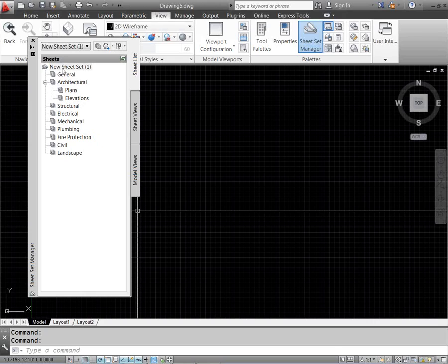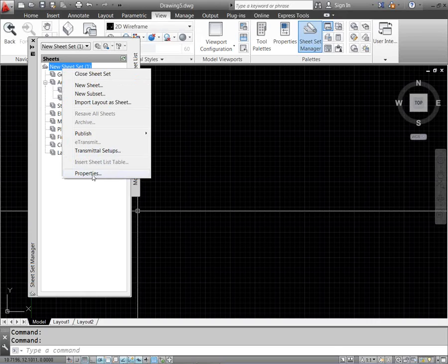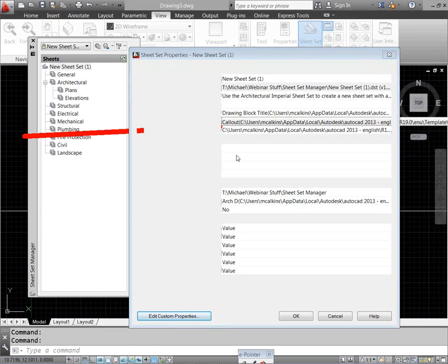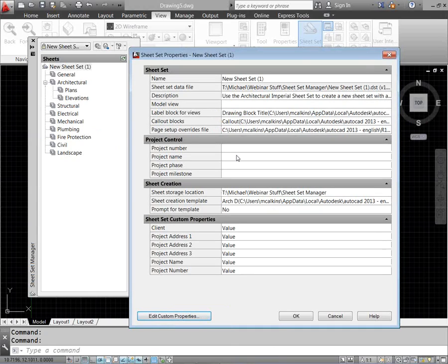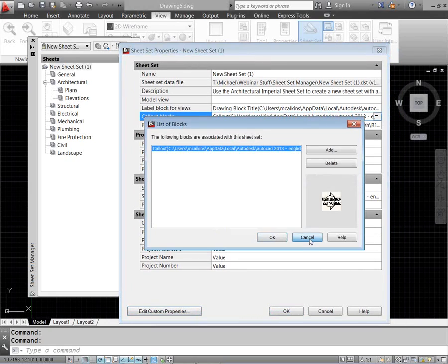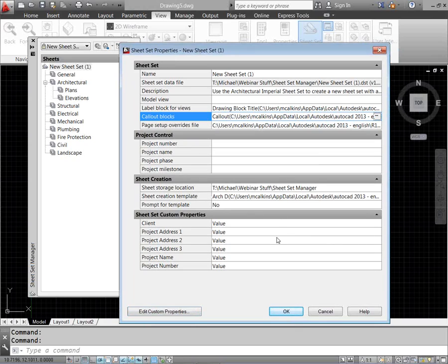And again, other things that will get saved to that example sheet set are here in the properties. Any of these things you see listed as a path. Mine are all going to the C drive. Yours would likely be pointed at your M drive for your AutoCAD standards, or whatever it is you use for your templates and content like that, office-wide content. Any of these are probably pointing at those locations, and that would already be saved as well. Instead of having to click on each of these and choose the ellipsis to repath every single one, these would already be set up, ready to go.